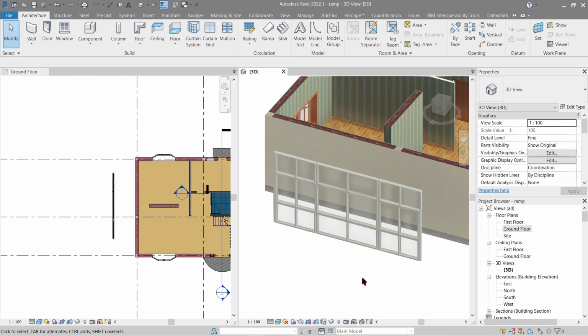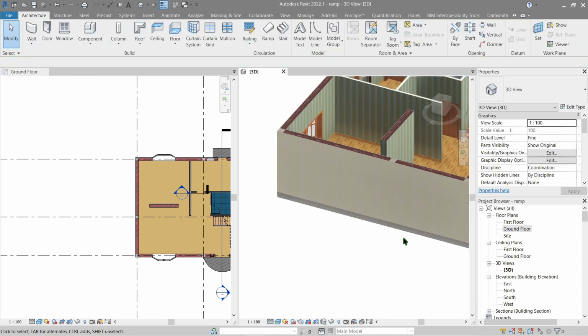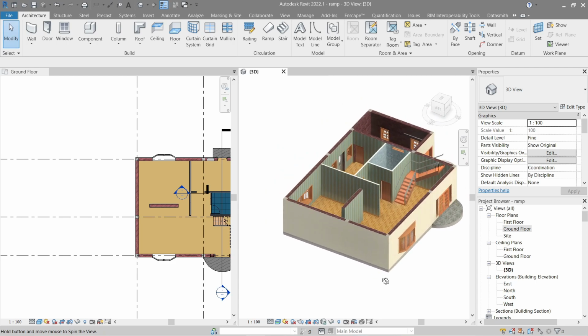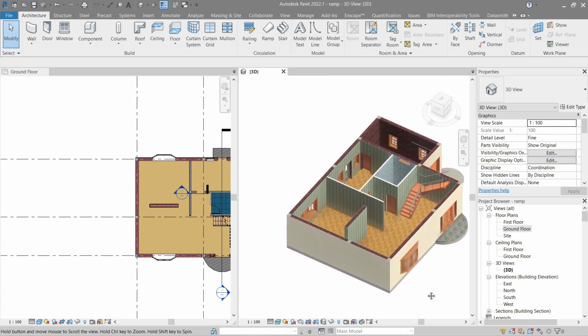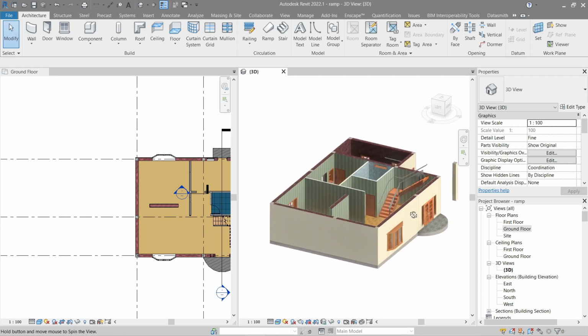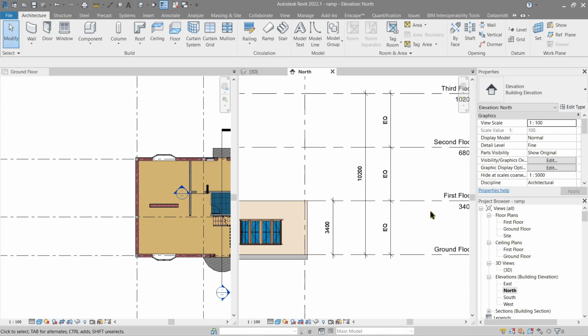Now finally, with that topic finished, let's go ahead and delete this one. I can't click it. Maybe if I click here. There we go. Delete. Now, let's make a curtain wall for the model that we have. But before we proceed, we gotta make our second floor first, as well as extend our walls to the second level. Let's go to elevation first and let's fix our level.